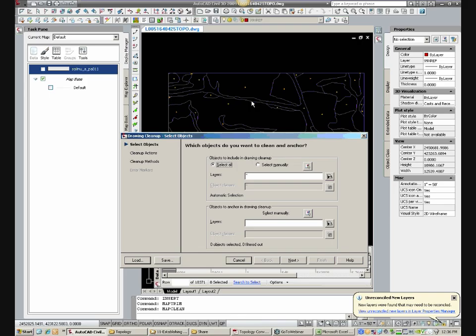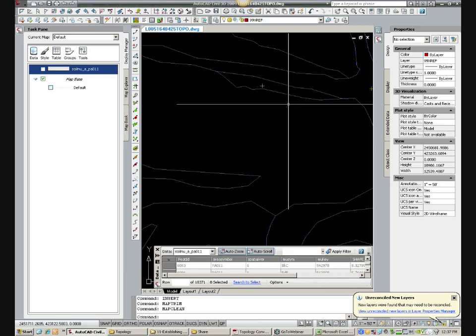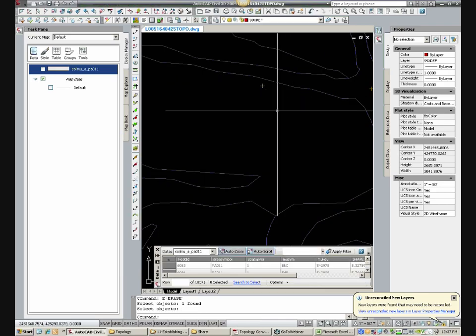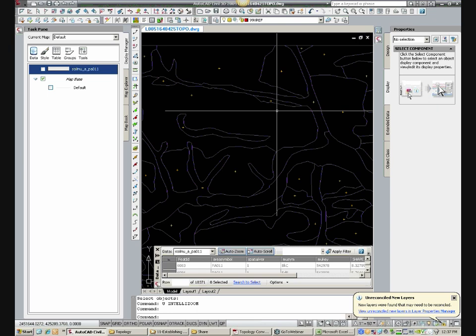You cannot have overlapping lines on the boundary. This boundary line cannot have a polyline for this enclosed area and then another one to outline the enclosed area over here. It has to be its own independent line. So there's only one line here, very similar to a parcel. Parcels are like that because parcels in the background are AutoCAD map topologies.